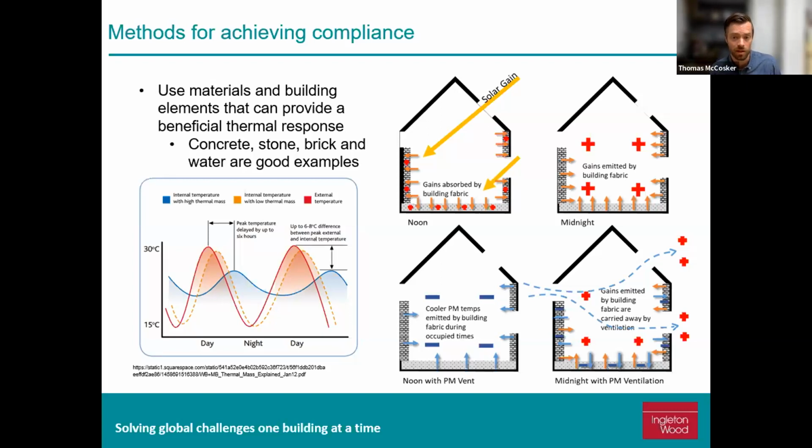Thermal mass does equalize the temperature, but it also rejects that heat back into the space. Dynamic thermal modeling takes that into account. And so you can see a benefit of including a massive floor system or a thermally massive ceiling, or in some cases, people include thermally massive internal walls.